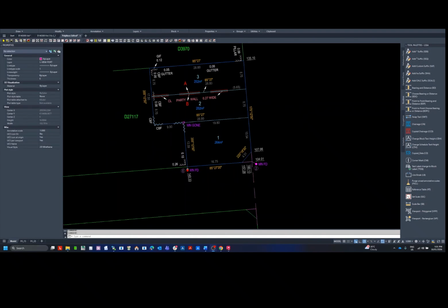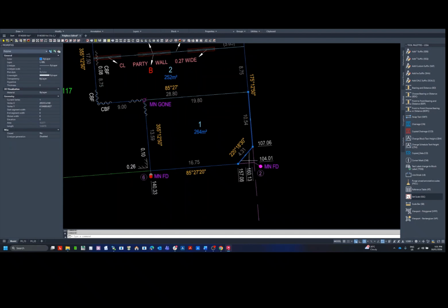Drafting tip number 5, polylines and natural boundaries. Avoid polylines for parcel boundaries when distance and bearing labels exist. So for a line like this, which is a polyline in your DWG, which has a distance label, a bearing label, and in this case a chainage label, our data processing will struggle to validate the distances against those lines as they are connected to each other. And therefore, validations will fail for these lines. And in your closures report, these lines will show up as missing data.